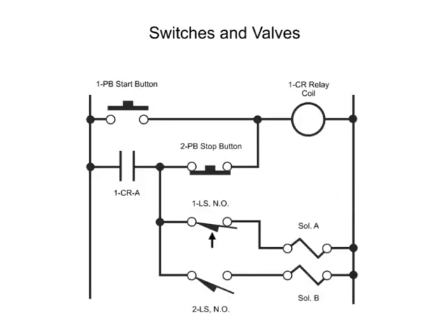For example, consider the limit switch, which is an electrical switch operated by the motion of a machine or presence of an object. In this circuit, there are two limit switches. Limit switch 1LS is a normally open switch. The arrow shown next to the switch indicates that the limit switch is normally opened, but is held closed prior to the start of the cycle. The other limit switch in this diagram is 2LS. It also is a normally open switch. However, at the start of the circuit, it is in the open position and thus has no arrow.